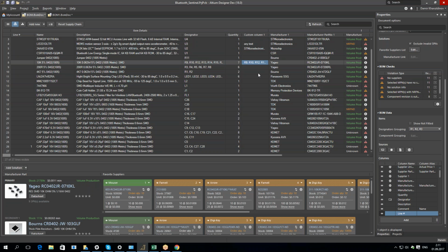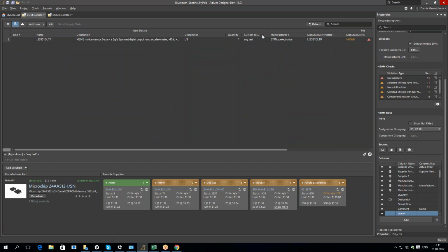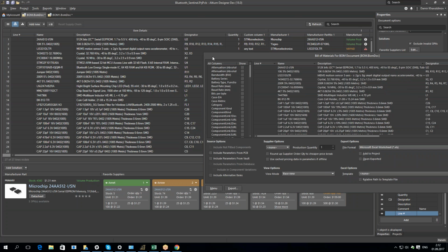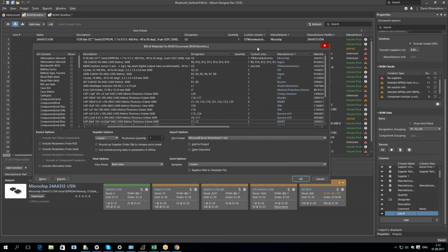You can filter after that, or use this field for some check marks. The beauty is that this data will be persistent and saved with the document itself and with the design, and will be available again everywhere. Whenever you export something, whenever you print, whenever you have your Draftsman, that's just a free text column, without updating your library or modifying the schematics.